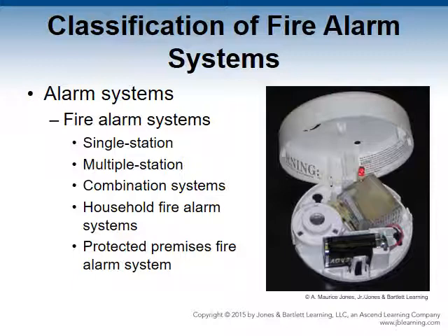The single station alarm system is an alarm/detector that operates independently from other alarm systems and detectors. They are also called a smoke alarm. They consist of an integrated sensing device, a power source, and an audible alarm, typically found in older homes built before they were mandatory requirements for smoke alarms in residential occupancies. No wiring is involved, so these are easy to install and are reasonably priced.